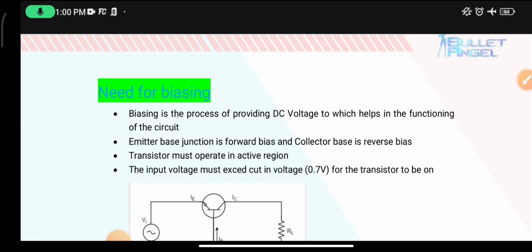Here the transistor can be used as an amplifier and as a switch. For the case of an amplifier, we provide DC voltage as follows. The emitter base junction is forward biased, meaning the input terminal must be forward biased, and the collector base junction is reverse biased, so the output terminal must be provided reverse bias. In this condition, the transistor can be used as an amplifier.